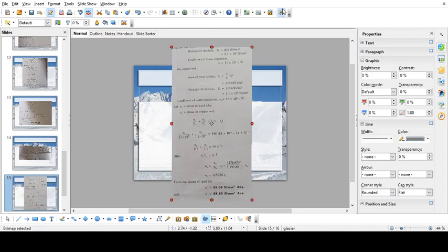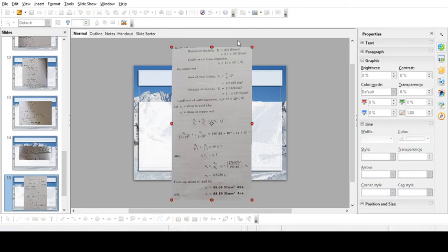So now if I take this, the modulus of elasticity of the copper rod is 110 kilonewton per mm square. We can write that in Newton. That is 110 into 10 to the power of 3 Newton per mm square. 110 can be written as 1.1 into 10 square. So it is simply 1.1 into 10 to the power of 5 Newton per mm square.